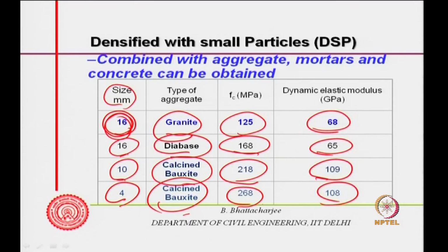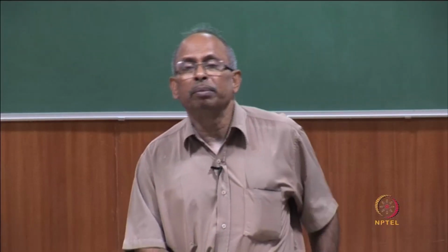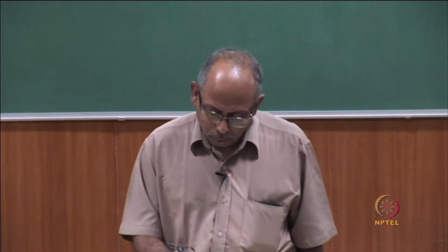So, you can see that you can go to fairly high strength, quite high strength, using this material when you are using aggregate. But higher MSA obviously gives you lower strength, because of stress concentration, non-uniformity, all that we talked about. When you have finer and no coarse aggregate, strength is much higher. So, another kind of material, which was developed originally in France and is possibly quite promising, of a similar sort of high strength matrices, is reactive powder concrete.